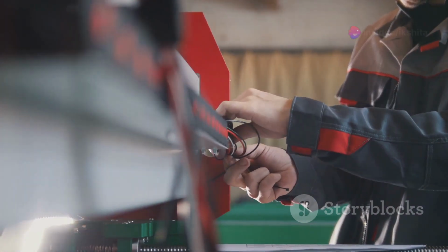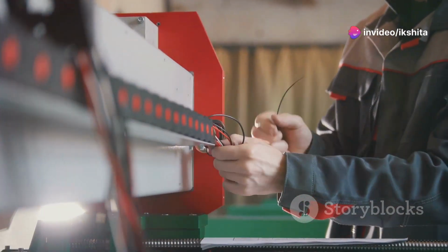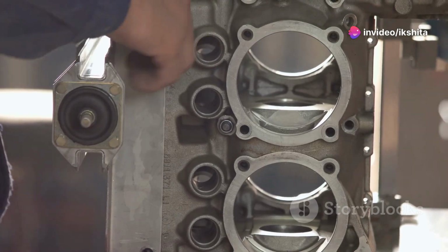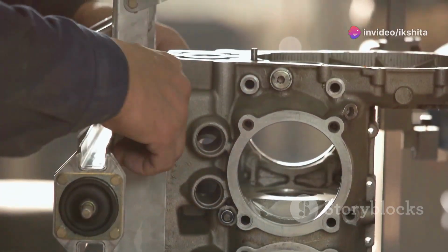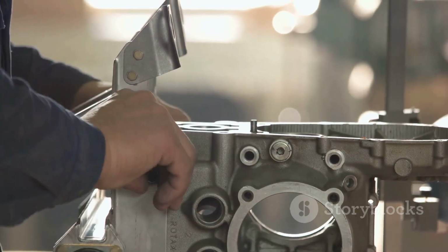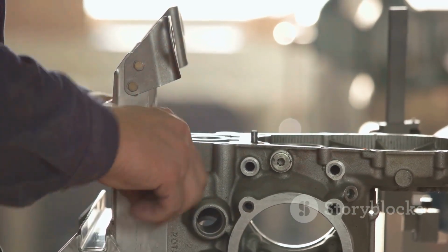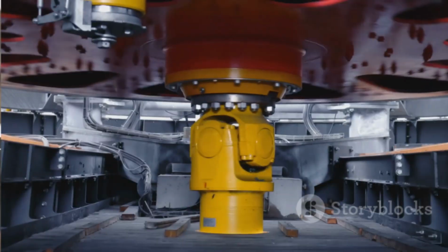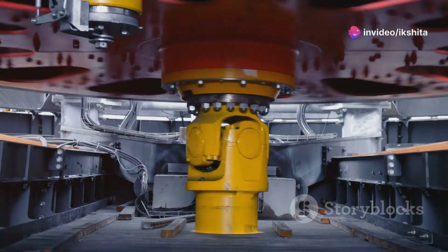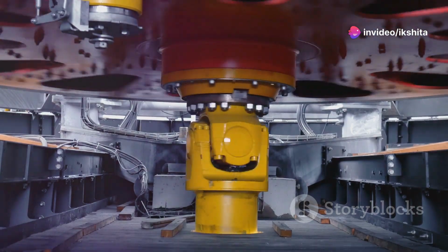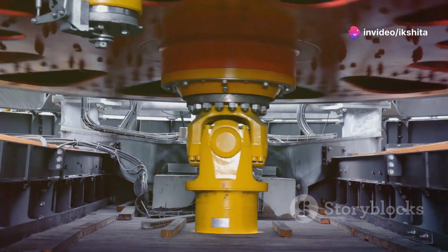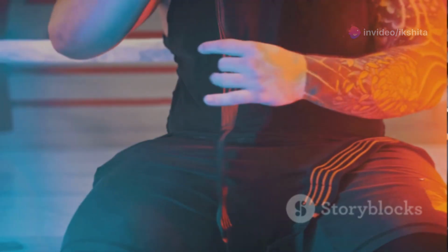Another technique involves adjusting the field excitation, the current supplied to the rotor's windings, to compensate for the changes caused by armature reaction. This adjustment is crucial for maintaining the desired performance levels. This helps maintain a stable magnetic field and consistent performance, which is vital for the longevity and reliability of the machinery. Think of it like adjusting the tension on a rubber band.